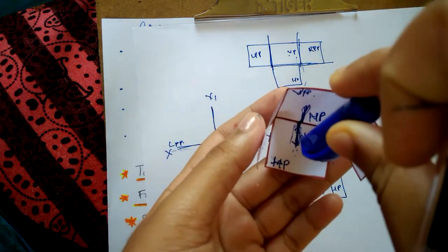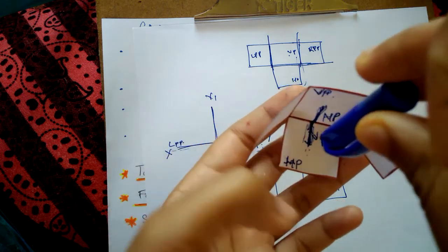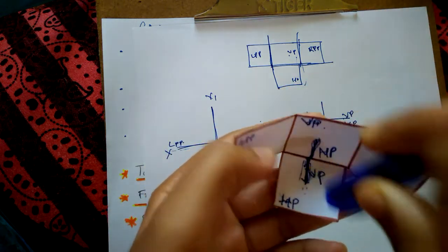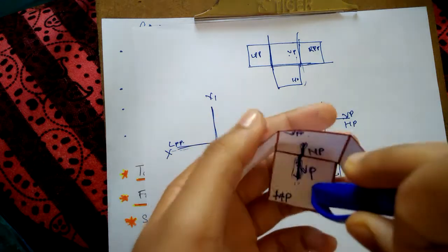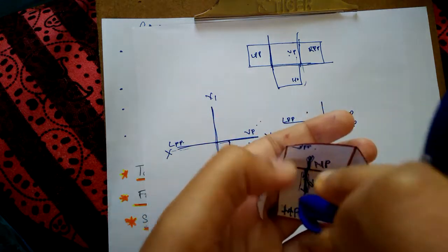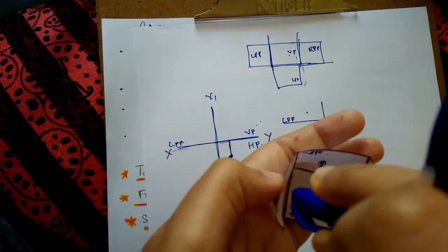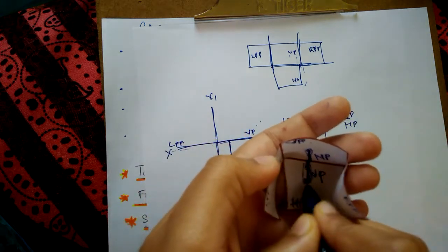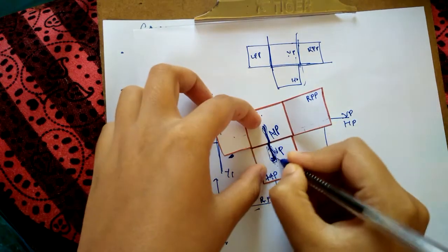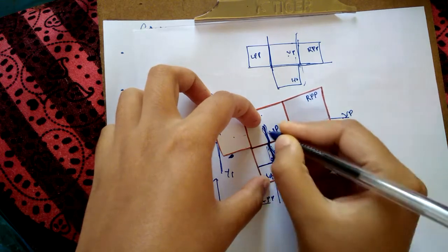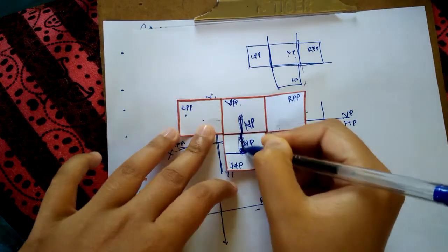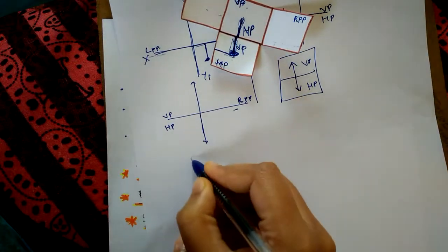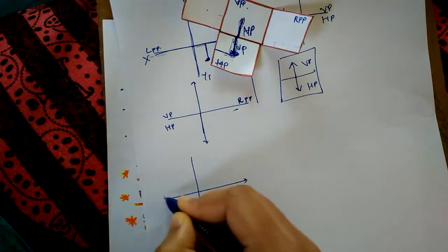So how would we draw it on a 2D paper? Since it was above HP, all the above distances were marked on VP, and all the frontal distances from VP were marked on HP. Similarly, it was 30 from LPP. The point lies here somewhere in air. So the distances come out to be something like these three lines. How do we represent it on a paper now?